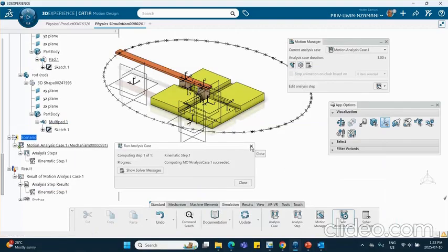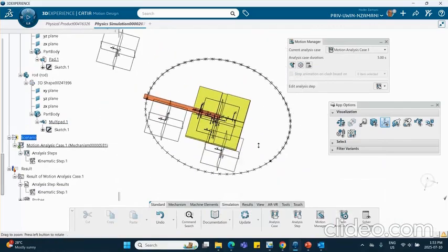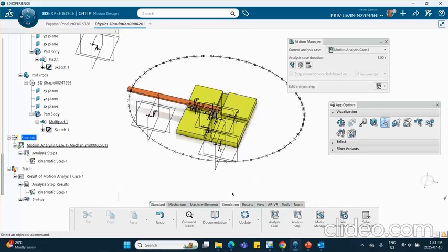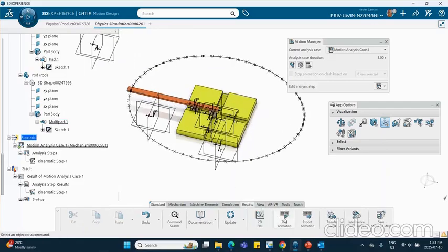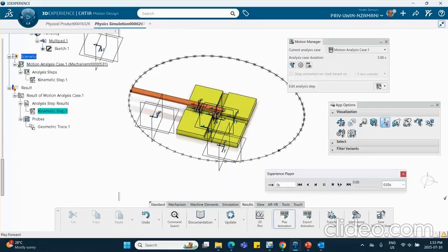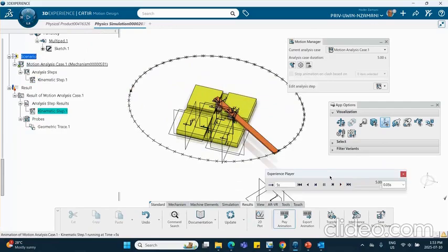There we are. This is an ellipse. Now, if this point happened to be exactly halfway between the two ends, that would be a circle. And you can always check this. Select this thing, not the probe. Select the file, animate, play. The tip traverses an ellipse.